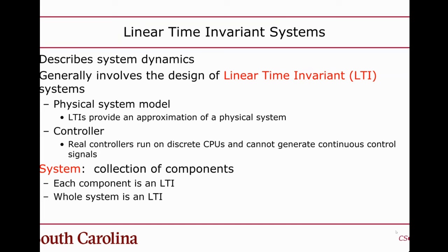So the problem, as I mentioned in the lecture, is that when you design a controller for an LTI, you typically design the controller also as an LTI. Well, that's a problem, because you can't actually implement a controller as an LTI, because LTIs are continuous and controllers are discrete because they run on computers.